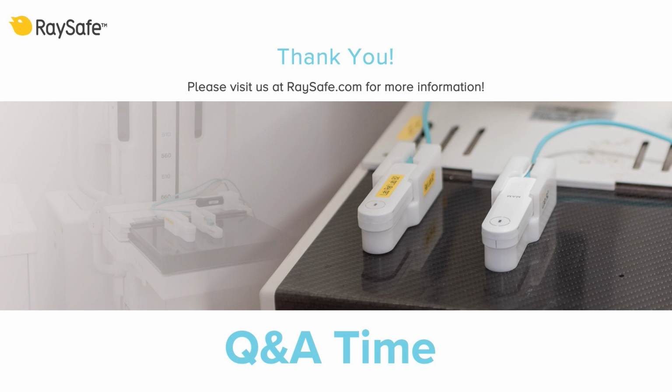What is a recommended calibration interval? Well, calibration always comes down to the user and how much the user trusts the instrument. And it also depends on how you have treated it. So we recommend a yearly calibration, which is according to many regulations, but I know there are people sending it every second year or third year as well. It depends on how it's used, more or less.